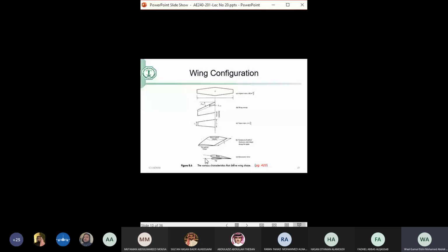Also, is there going to be any twist in the wing? Just like the propeller, we can twist the wing, changing the angle of attack between the root and the tip sections. Sometimes this gives important aircraft handling qualities. I would find this even more important in your design project than in this example, because it will affect the way the lift distribution exists on the aircraft.